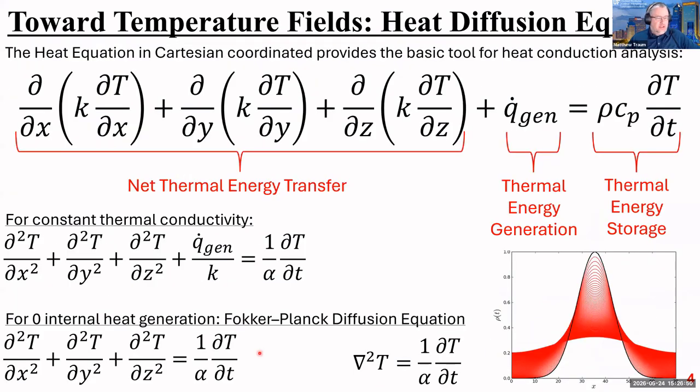And so the first thing that we're going to do to simplify to what's commonly the heat diffusion equation is we're going to imagine that K, the thermal conductivity, is constant, not a function of temperature, which we talked about in the previous lecture as the standard assumption that usually gets made for thermal conductivity, although you do know how to calculate situations where K changes with temperature, because we just talked about that in lecture two. So for now we'll assume that K is a constant value.